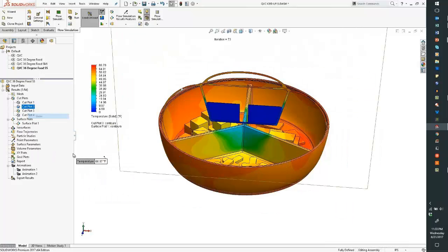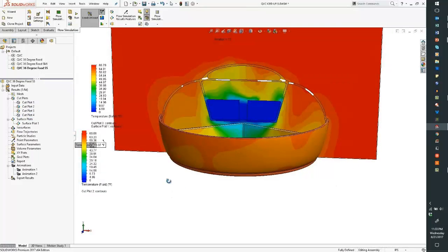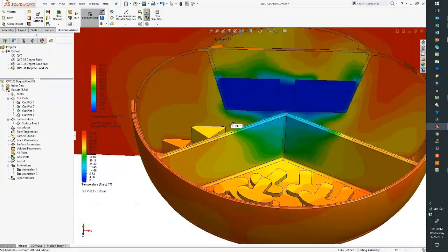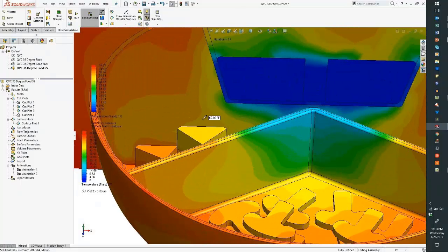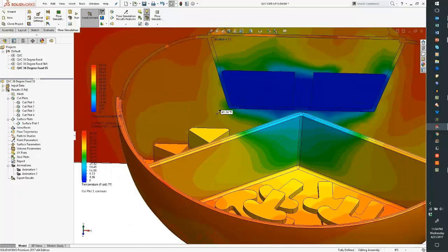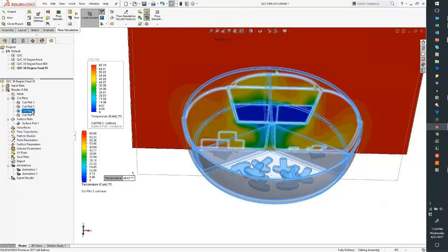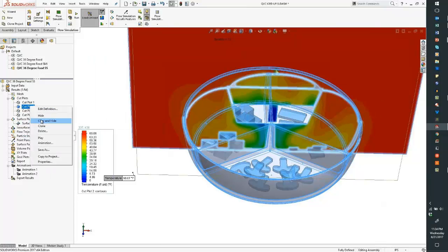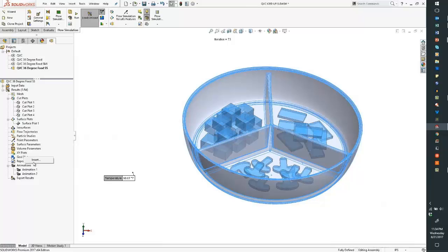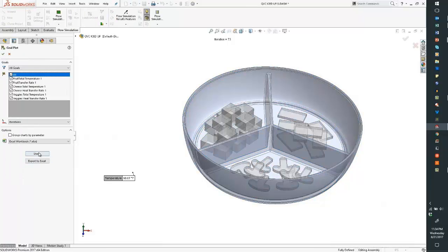Yeah, a fan would be a good option to circulate the air inside of there. Now it's a forced convection type problem. That would certainly work. But because we're right inside of SOLIDWORKS, we can leverage that data so we can make these ribs thicker. We can maybe change the materials of the bottom of this. And I personally would probably put the ice underneath to have it conduct through to the vegetables, as well as do some natural convection in there as well.